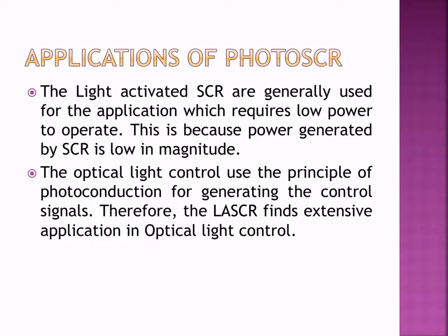Applications of PhotoSCR. The light-activated SCRs are generally used for applications which require low power to operate. This is because the power generated by the SCR is low in magnitude. The optical light control uses the principle of photoconduction for generating the control signals. Therefore, the LASCR finds extensive application in optical light control.